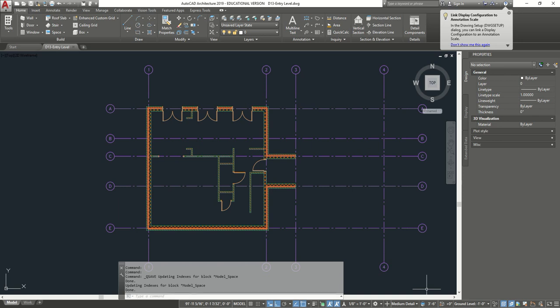Alright, so now we're going to reposition the patio doors within the walls. So the frame thickness of the patio door will change, and the patio doors have to move along the wall thickness so that the exterior face of their frames and interior faces of the insulation fall in line.